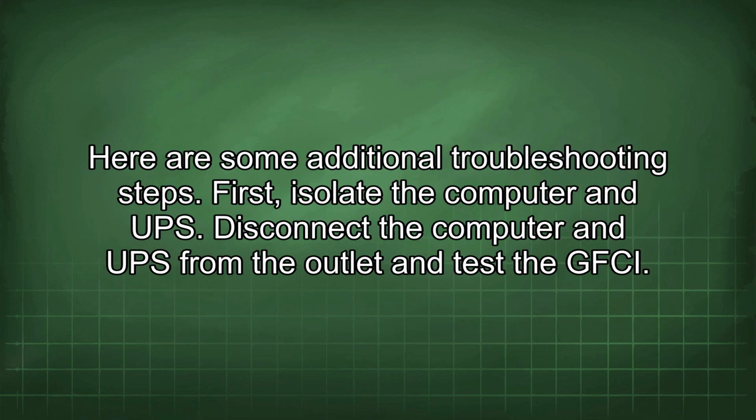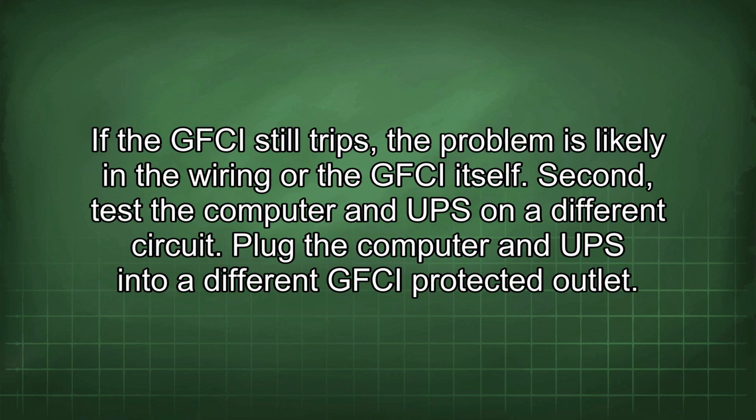Here are some additional troubleshooting steps. First, isolate the computer and UPS. Disconnect the computer and UPS from the outlet and test the GFCI. If the GFCI still trips, the problem is likely in the wiring or the GFCI itself.